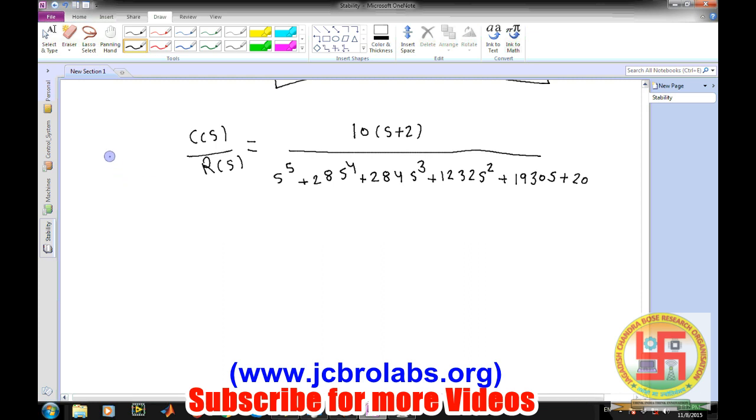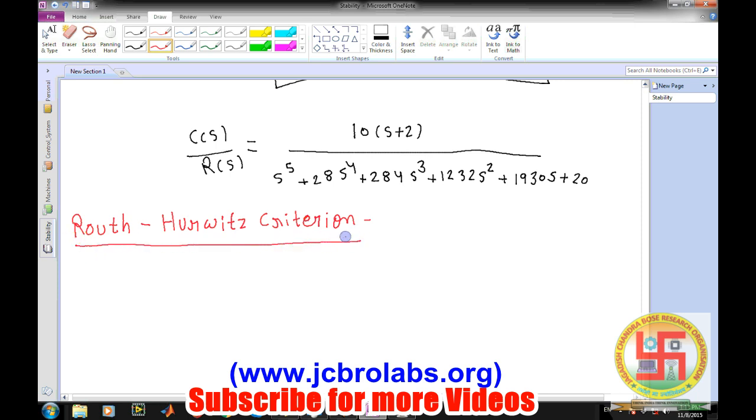There is a criterion to solve our problem, known as the Routh-Hurwitz criterion. Routh and Hurwitz came up with a method by which, without finding the exact roots of this transfer function, we can say this many roots are lying on the right side of the S-plane and this many on the left side, and from that we can estimate whether our system is stable or unstable.